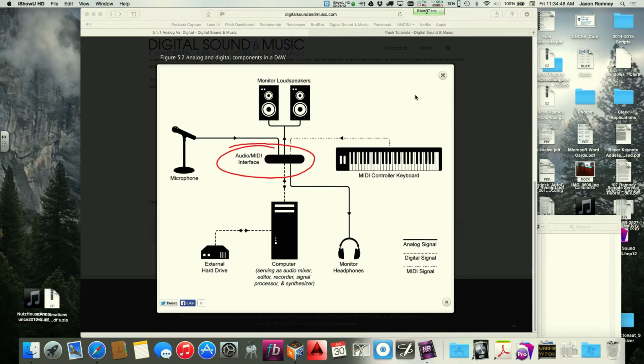As you may or may not know, AVB is a standard that is being developed where you could use standard computer networking to shoot the audio around. So essentially you're going to use the Ethernet connection on your computer for your audio interfacing. You can get little pieces of software that will let your sound programs send audio through your Ethernet connection. In fact, most new Macs come out of the box with this capability, so you can turn on AVB for your network port, and it'll shoot audio down there. Now you have to have something on the other end to receive it, but you can get it.